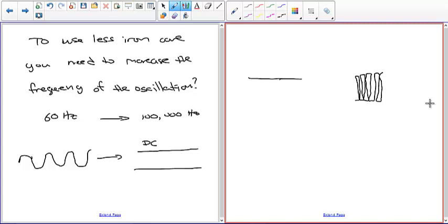That is the alternating signal that goes into the core and transforms to the secondary loop to change the voltage, which again depends upon the number of loops. But because the oscillations are so quick, d phi dt is huge; the rate of change in the magnetic field is huge because it's happening so quickly.